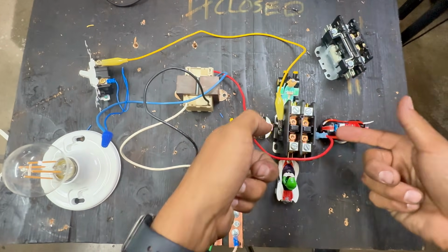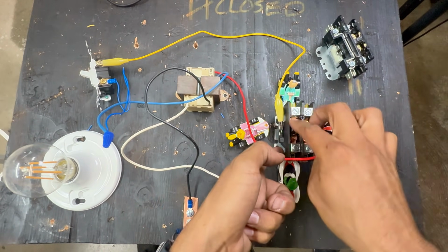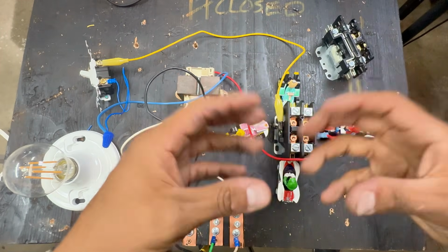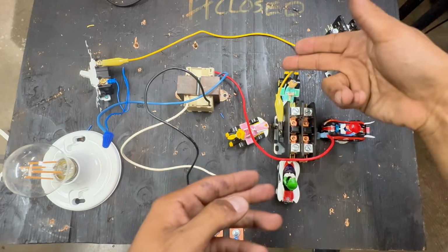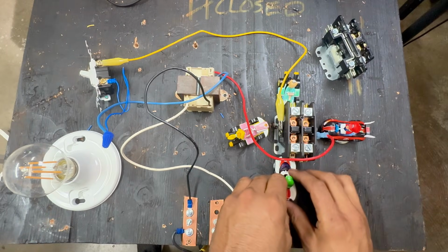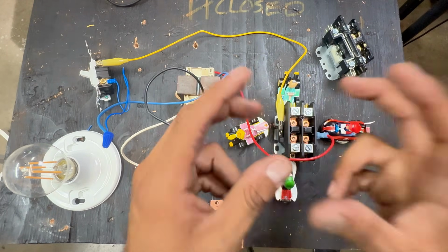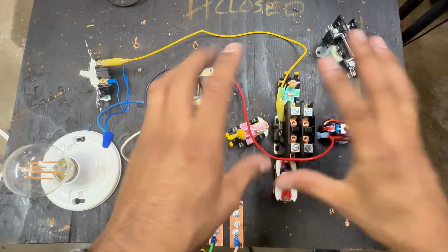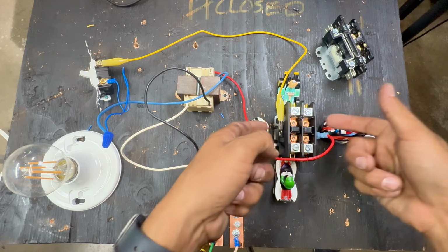We're sending low voltage so that we can close the bridge, and then high voltage can go through to turn on the compressor. In this case, Rosalinda can meet with Luigi, right? So if you understood that, the high voltage is already wired for you. We just have to troubleshoot the low voltage.